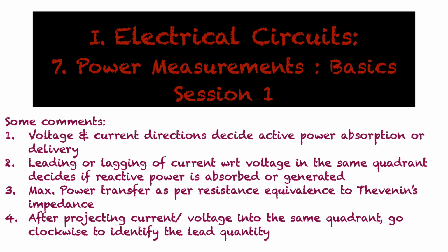So one of them is reflected back such that both voltage and current phases are in the same quadrant, and then you go in the clockwise direction to see what is leading. If what you encounter first is voltage, then you say that the current lags, so it's actually absorbing reactive power, because it indicates an inductor.